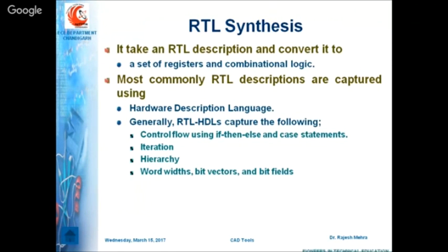RTL synthesis, we discussed this yesterday also. You have the option in your design: either you can input your design in the form of a schematic, or you can input your design in the form of VHDL or Verilog code. If you input your design in the form of VHDL or Verilog code, then RTL synthesis is going to take that textual code and convert it into its RTL description.